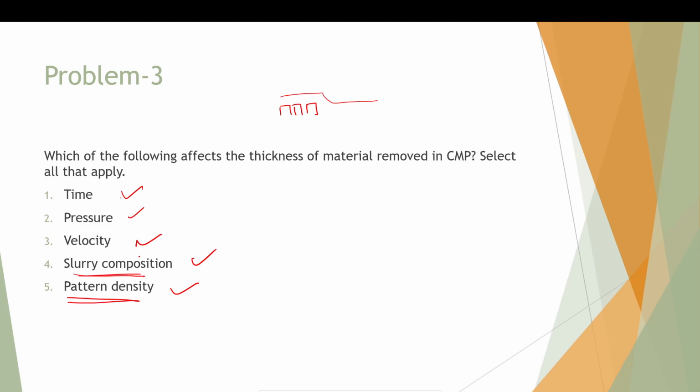Slurry composition, because that will dictate the chemistry, and also what abrasives are present in the slurry. And velocity, pressure, and time, we can say from the Preston model. Yeah, you're right. So I'll just write the Preston model.